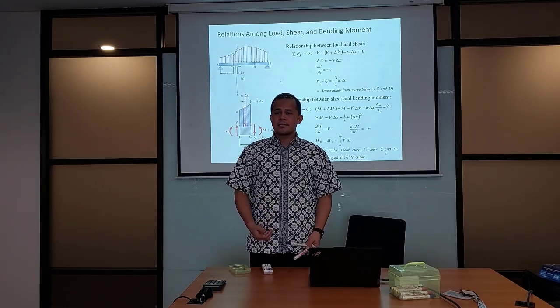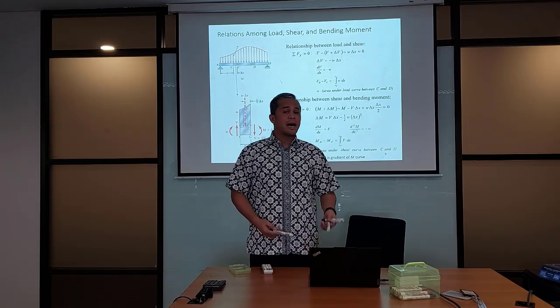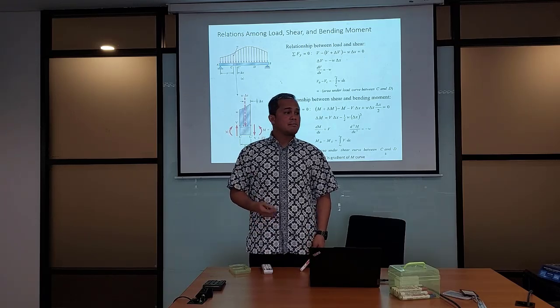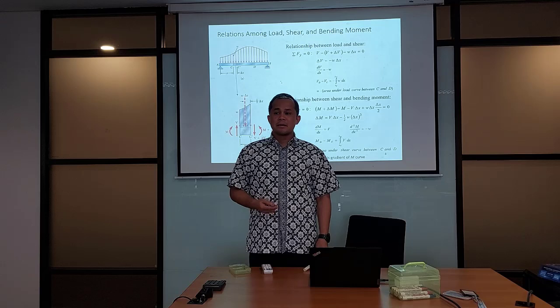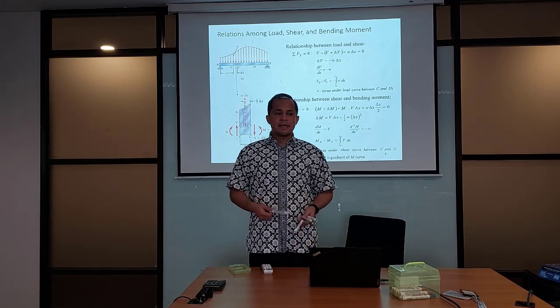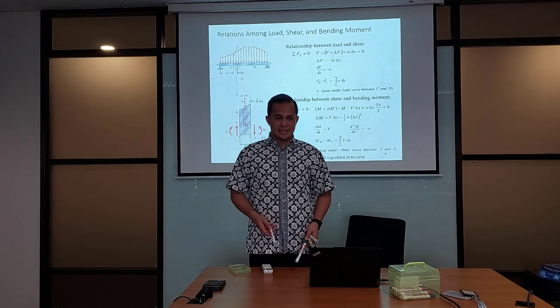The purpose of us doing SFD and BMD is to find the location of the maximum shear force and the maximum bending moment. Because by knowing that, we know the particular location where the beam may fail. Therefore, we would like to quantify the stress.